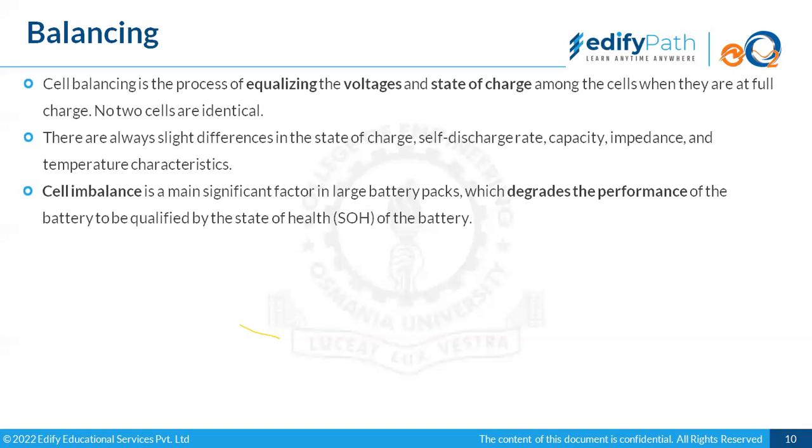So every cell should be contributing such that every cell is fully charged and every cell is showing equal voltage. Individually, if we check the cells, say it is comprised of 500 or 600 cells, every cell is at an equal voltage. That we will call a balanced battery.